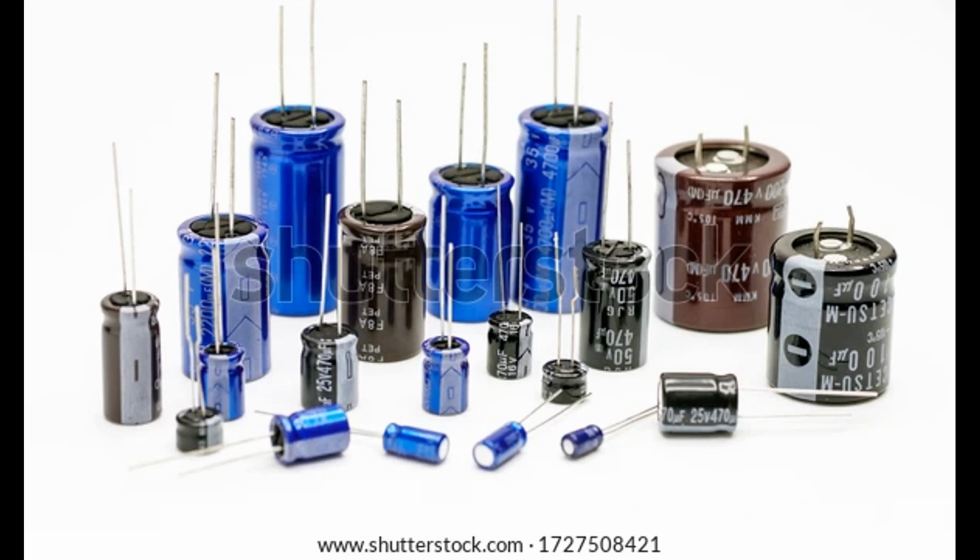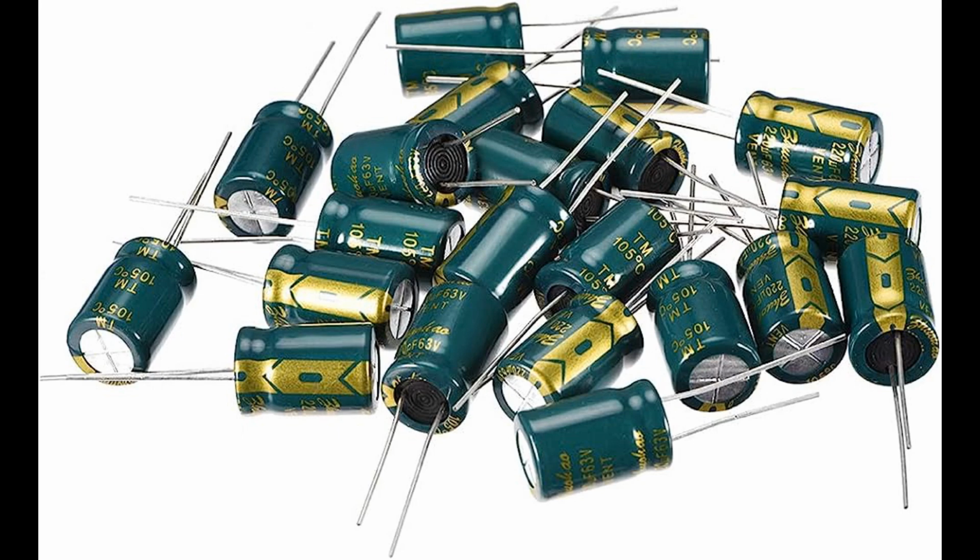Capacitors with high capacitance values tend to be physically larger due to the need for larger electrode surface areas or additional dielectric layers. They are available in various form factors, including radial leaded capacitors, axial leaded capacitors, and surface mount technology (SMT) capacitors. The size and form factor of high capacitance capacitors should be considered in circuit design, particularly in space-constrained applications.